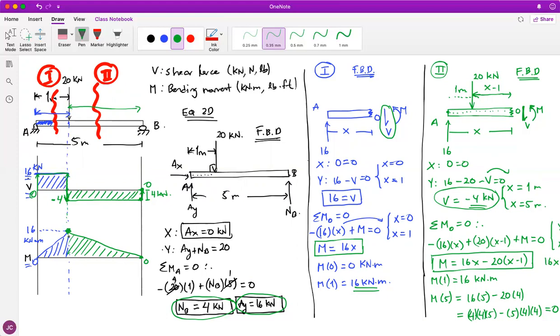So you need to be careful. It's not that you need to be careful, okay? But you need to be aware that when the shear force gets to a value of 0, you will have a maximum or maybe a minimum for the bending moment. And those are points of reference. You need to be aware of those points because there's something telling you maybe this thing is gonna happen for the beam, or maybe I shouldn't load too much. I shouldn't put a 20 kilonewton over there because maybe this guy fails or the material fails or maybe it just breaks up. Those things are part of another more complicated analysis.